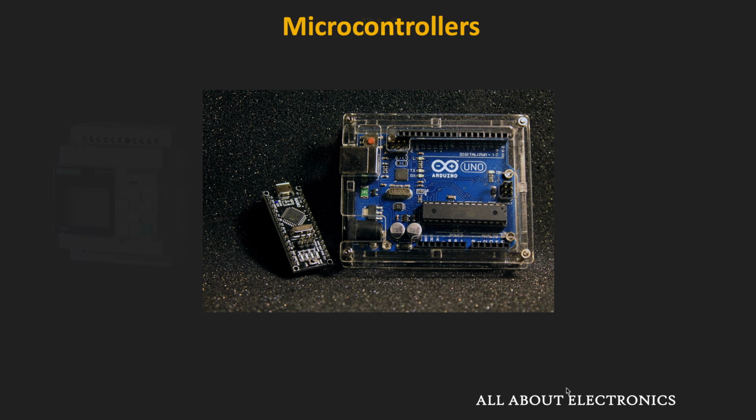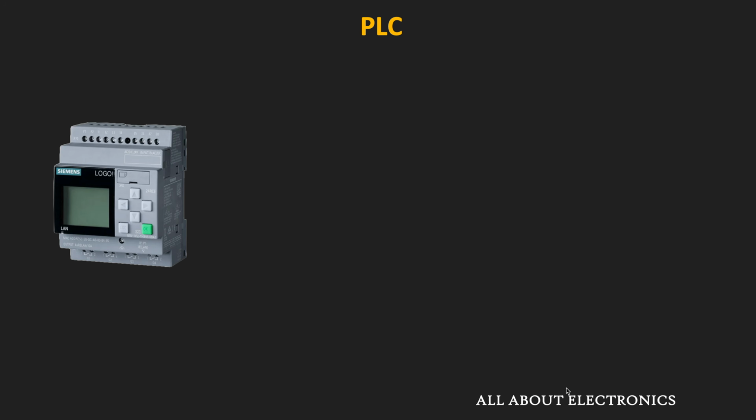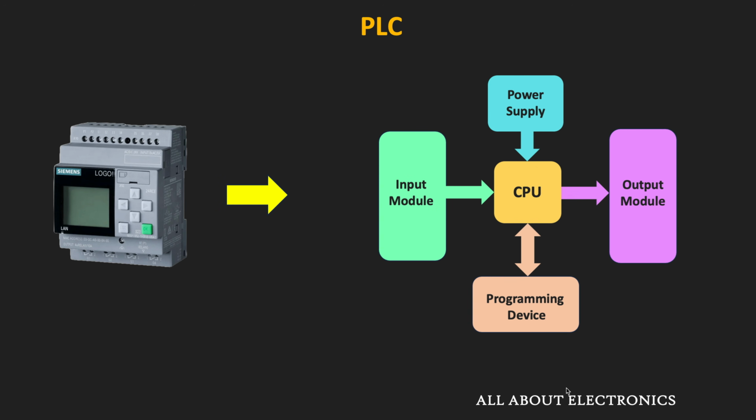So this PLC or the programmable logic controller is the industrial controller which consists of the following modules. So if you see in the heart of it, then it consists of the CPU and the relevant program and the data memories. And apart from that, it consists of the input and the output modules. So through this input module, different sensors and the switches can be integrated with the controller. And through this output module, different actuators can be switched on and off.